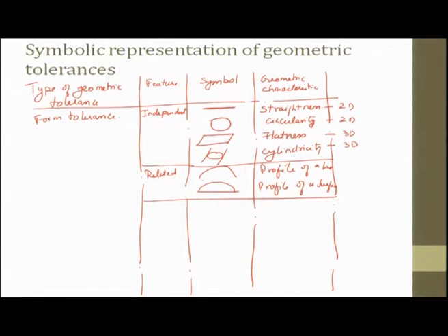We were talking about, so this is perpendicularity. Can you think of an example where this is very important? Wherever you have something like an L angle you want to measure, or if there is a channel like this, you want to measure its 90 degrees, there might be some requirement. So then we talk about the perpendicularity of it. Then we also talk about parallelism, then angularity,